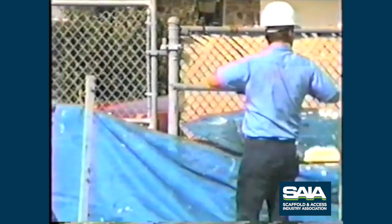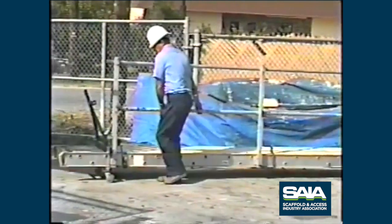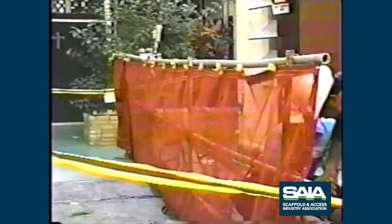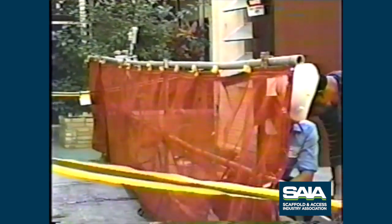A guardrail system is required even when fall arrest equipment is used. Install sufficient guardrail posts to adequately support the guardrail system. Where persons are required to work or pass under the scaffold, install a safety screen or equivalent between the toe board and top rail. Precautions must be taken to prevent the scaffold from damage when acids or other corrosive substances are used.